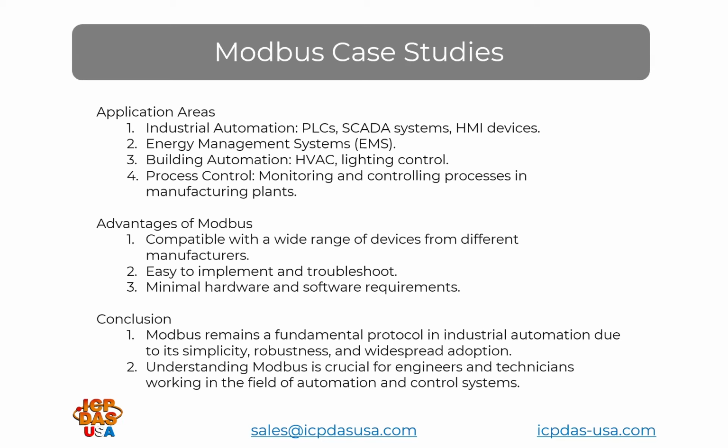Speaking of opposites, how do you deal with your registers being off by one? Is there a standard practice for that? Because that's so common. Well, that has to do with PLC addressing versus, I forget what the other one was. Ideally, if the register starts with 30,000, then it's zero based. If it starts with 30,001, then it's one based. Within the Modbus command, in most software packages you just need to specify the actual register that you're writing to, so it'd be like the 30,001. And some of them actually have a little radio button or a choice to specify if you want it one based or zero based.